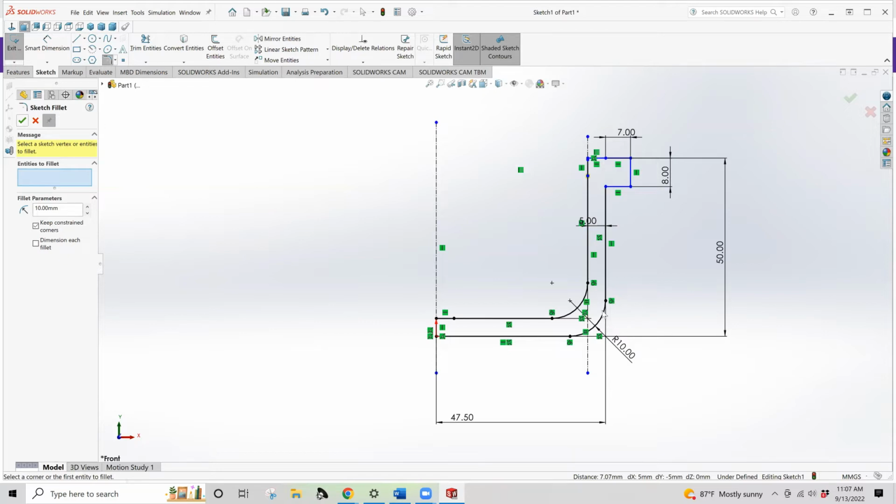So when we do this, we end up with a radius in our part. We could have done this with an arc, but in order to do that, we would have to guess at where the center point would be, set up the arc, and then do some smart dimensioning. So it's about 6 or 8 steps to do it manually versus coming in, picking the point where you have 2 straight lines intersecting, and then making these parallel. You'll note that even though they're parallel, the absolute thickness of those two is not exactly consistent, which is actually very much like a real life casting from an object.